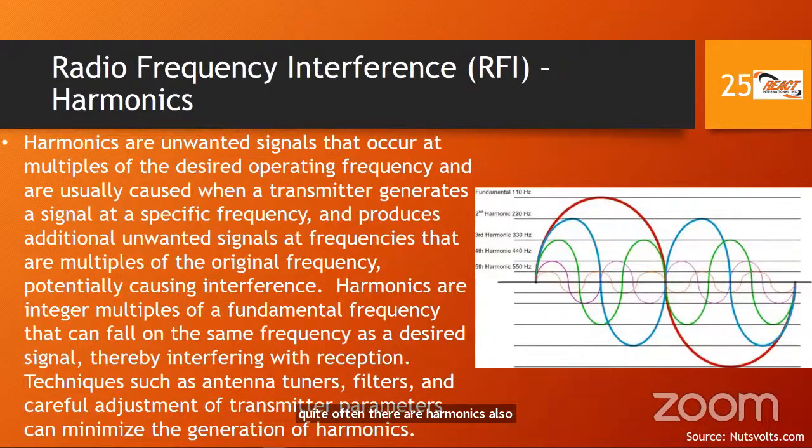What do we mean by that? So if I am generating a frequency, let's say 7.159 megahertz, when my transmitter generates that frequency, it is also generating multiples of that frequency that are called harmonics. So it generates the second harmonic, the third harmonic, the fourth harmonic, which is a multiplier of the original frequency. It generates that. So radio transceivers should have filter stages that filter these out.